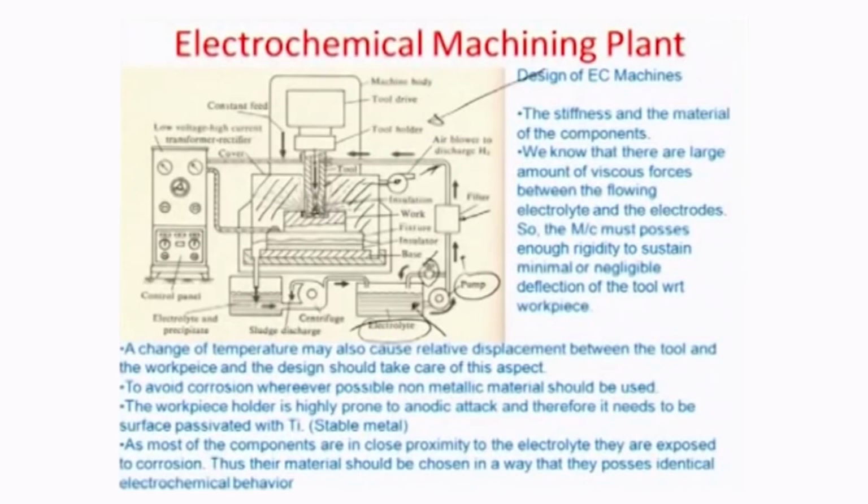So there should be a discharge port for the byproducts of the chemical reaction coming out, and of course there can be a way that you can recirculate the electrolyte. So you can either precipitate and do a sludge discharging, okay, so that whatever electrolyte you can recover here can be recirculated back, although it is really not a very good idea to do that.